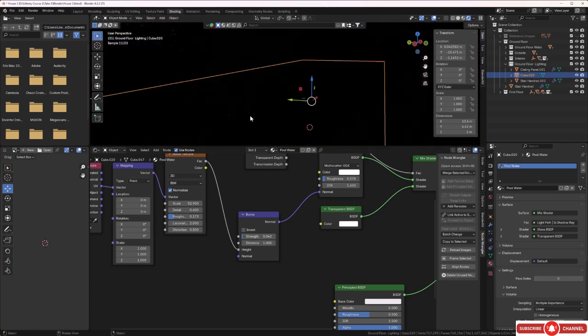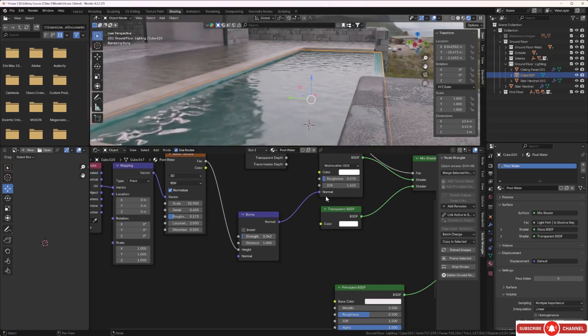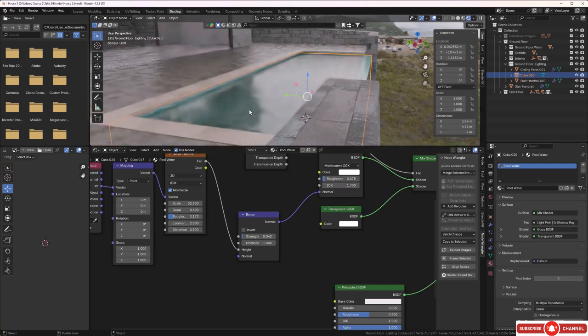And there we go, that's pretty nice now. I'm liking that. We could try adjusting the IOR here again. At 9, it's just too reflective. So I think we were going the right way, actually. I don't think it was far off. And that's not bad just there.